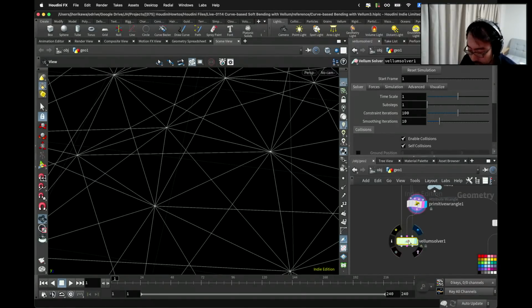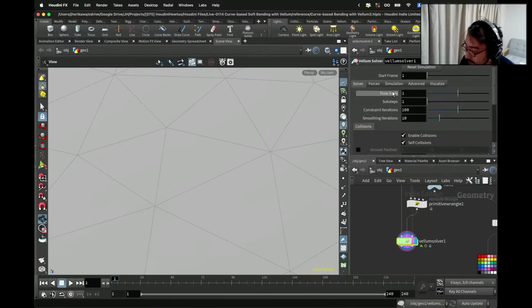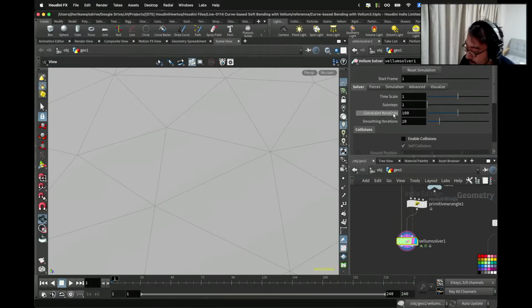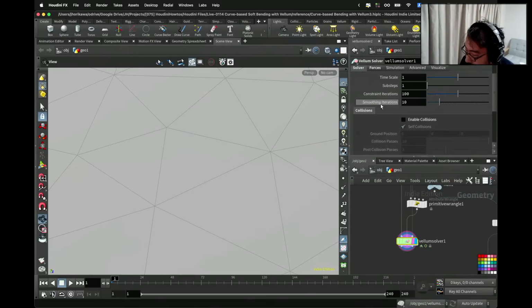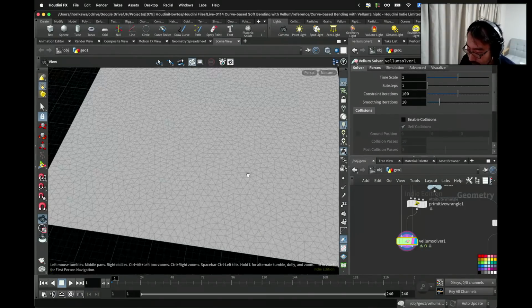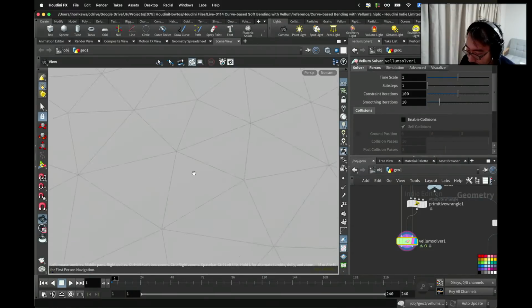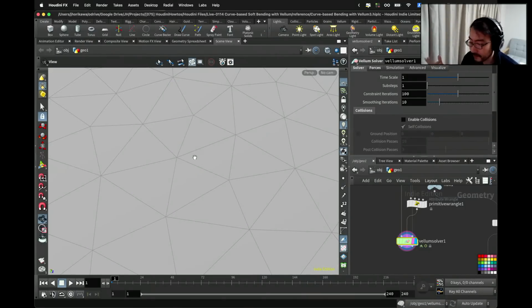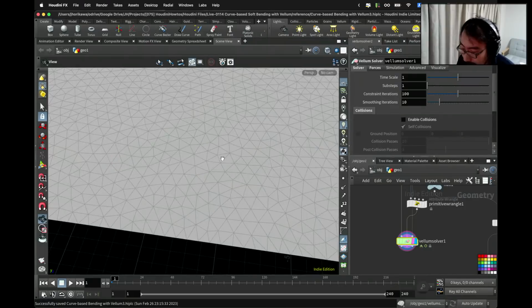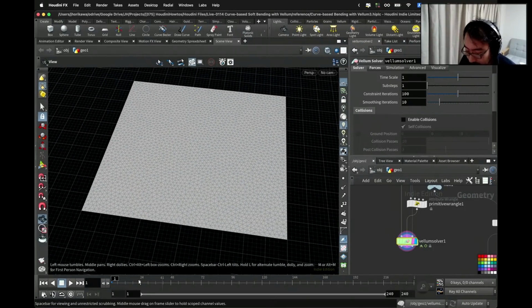Okay, and also I am going to disable the collision for now, as well as gravity, so that I can do a quick simulation test. Okay, so let's see what happens. Every pair of triangles has a constraint, and I have just set the rest length, which is going to be used as the rest constraint angle, to be 30. So let's see what happens if I play it.